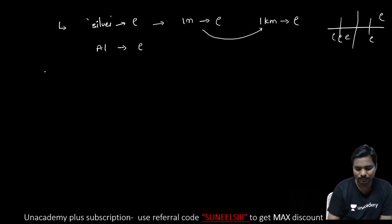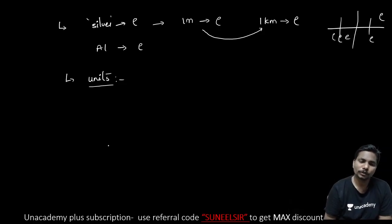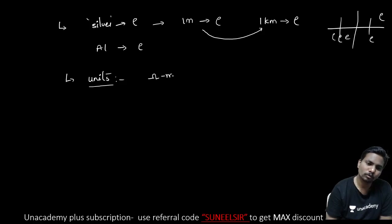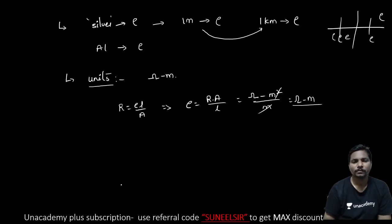And one more thing is the units. Coming to the units, the unit is ohm meter. We know very well R is equal to rho L by A. So from this, rho is equal to R into A by L. Resistance units are ohms, area is meter square, length is meter. So one meter gets cancelled out, and you get ohm meter. So ohm meter is the unit of resistivity or specific resistance.